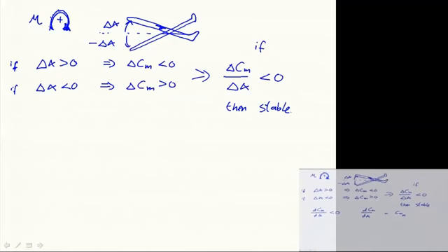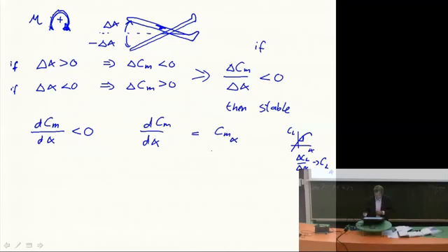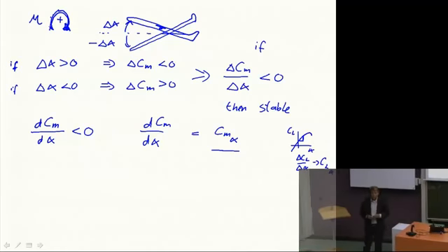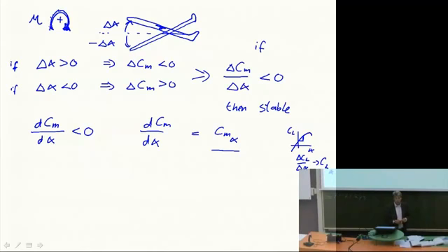So similarly, you could say if we look at the angle of the CL alpha curve, and we look at the steepness of it, we call that dCl d alpha, and that we also write as CL alpha. So this is a form of notation. If you see a second index, this often refers to either a 0, being the neutral, or a place, but if it's an alpha, it means the change of this coefficient due to a change in alpha, because that's where the derivative stands for, right? Delta y delta x was the change of the y per x. So this is the change of the pitching moment per alpha. Or if you say it correctly, it's the change of the dimensionless pitching moment per degree alpha.